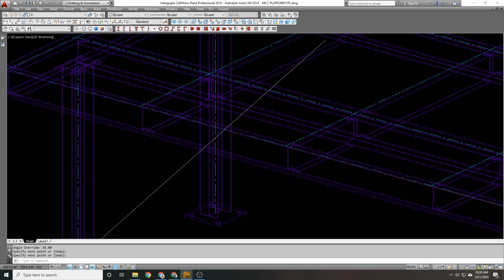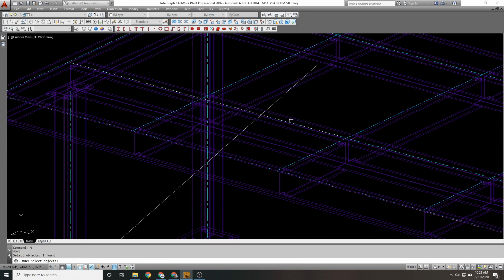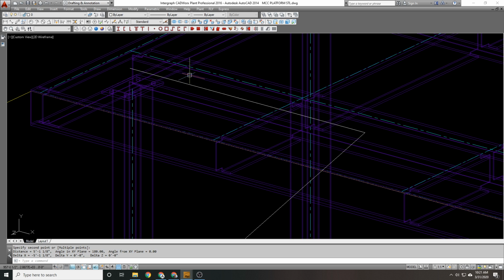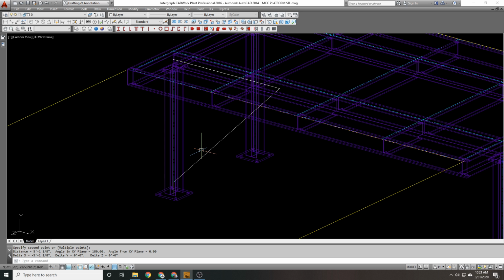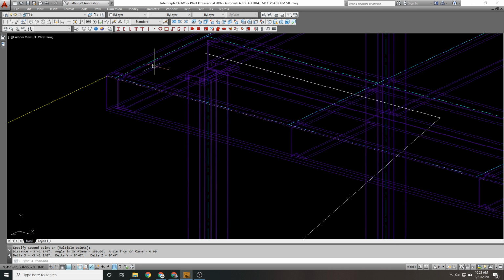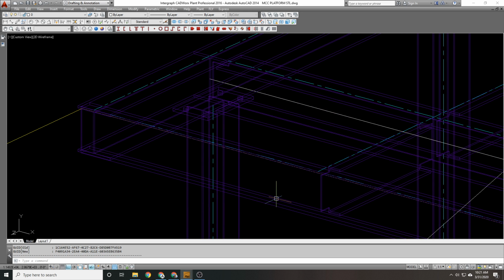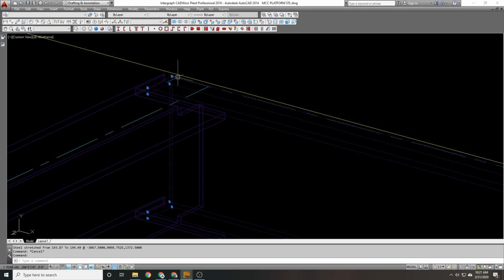And wherever this lands, let's see. Over here, I want to take this down 4 inches because this is a W8. And that's where these 2 are. So let's see, what was this work point? 5 foot 1 1/8. I'm not a big fan of that, and it's because this is a W8x18. I just realized this has to be a W8x24. Why didn't you guys tell me that? I'm gonna have to recope and bring this out to here. I did the one side, I did not do this side.